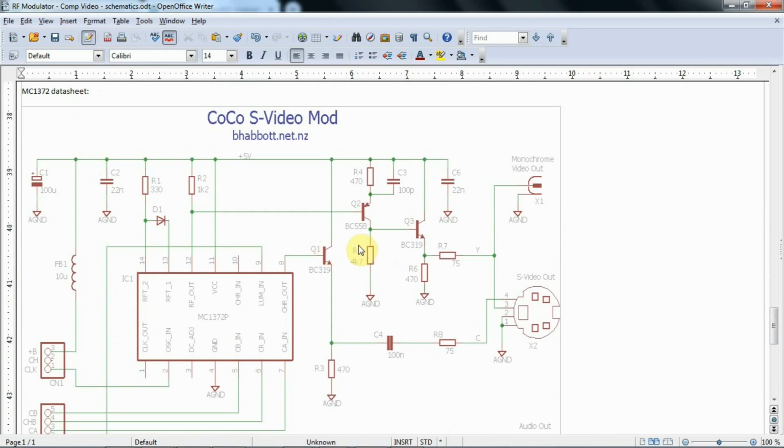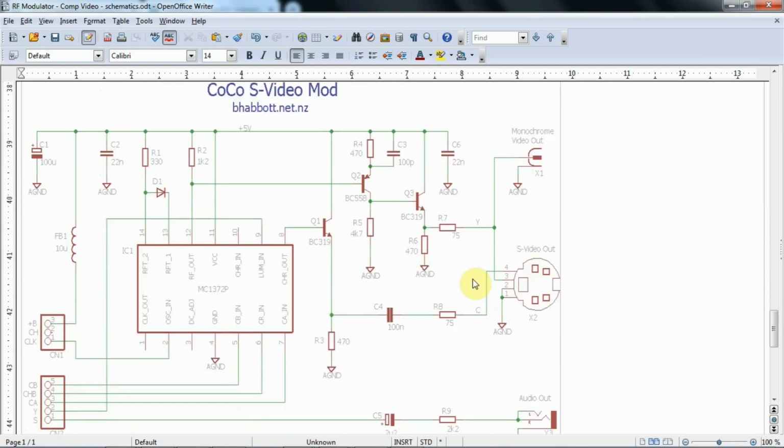Okay, then I found this. I found this very late in my investigation, but it shows an approach toward creating S-Video. And it's basically taking the old circuit from the 6847's data sheet, but just repurposing it using a different load value here, and then repurposing it toward creating a Y only signal, or luminance only, for the S-Video connector. And then the chroma signal is coming off of the pin 8 output.